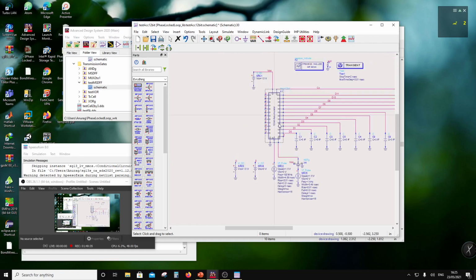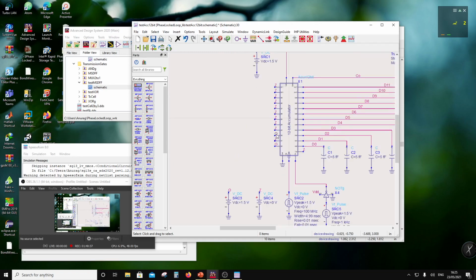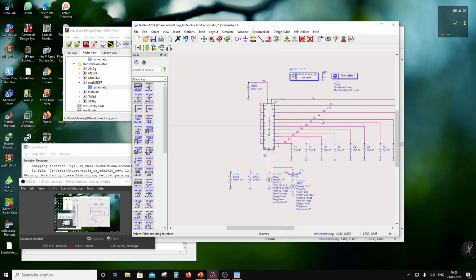So I'm going to clear that with this pulse at 1 nanosecond, and then at 5 nanoseconds I'm going to start the clock, and that will do a 5, then 10, and then 15, and then 15 plus 10 is 25, 25 plus 15 is 40, and so on. So that's what this output is going to be, correct? And here, actually 100 megahertz, right?